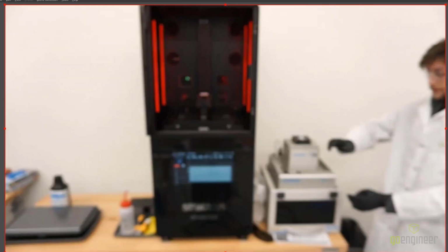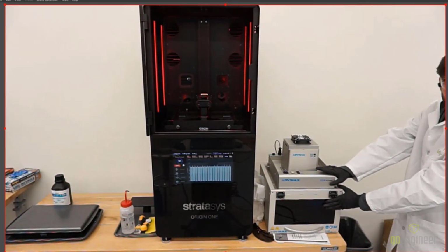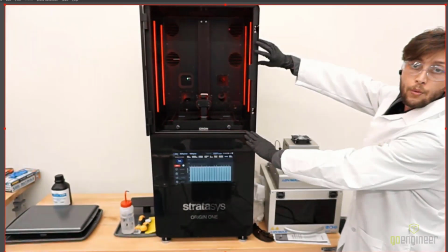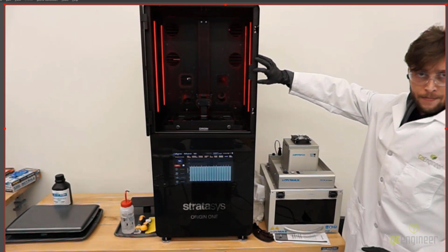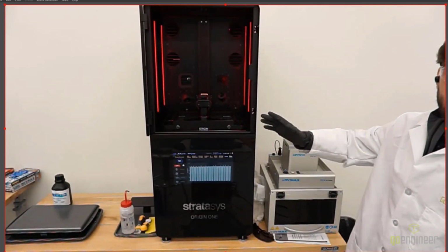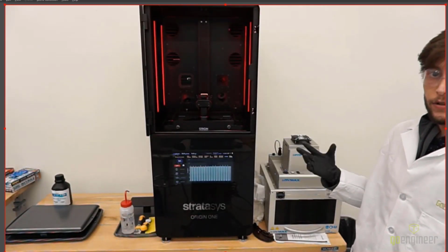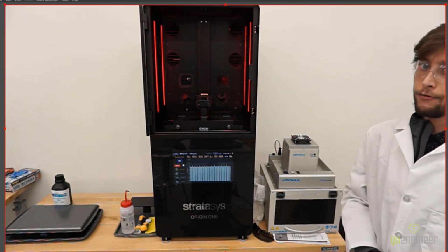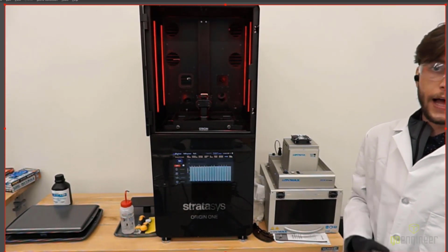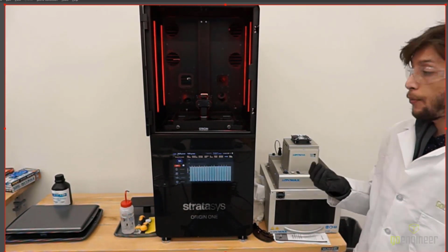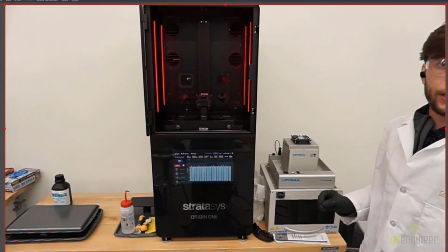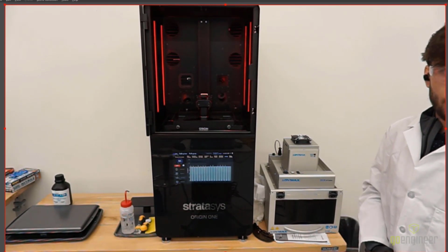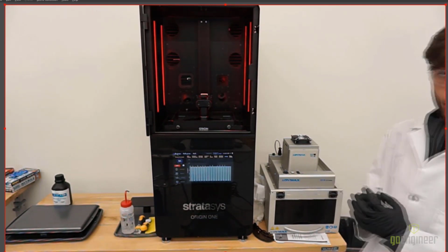To what would be the right on the screen, I have a UV cure chamber. This is used to cure the parts after they come out of the machine and they have been washed. Typical wash time is about 5 minutes, and then you need to wait about 10 minutes to 1 hour for that part to dry. If you do not wait for that part to dry, it might have some residue that will show up white in the chamber. Very, very thin walls have a tendency to swell up. By letting them dry out, they will return back to their normal shape before cure.